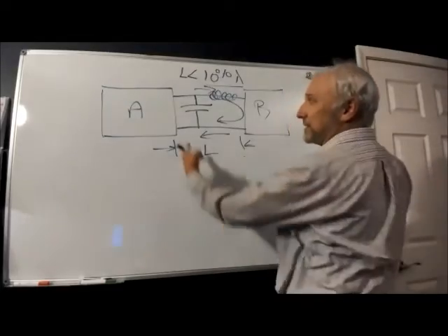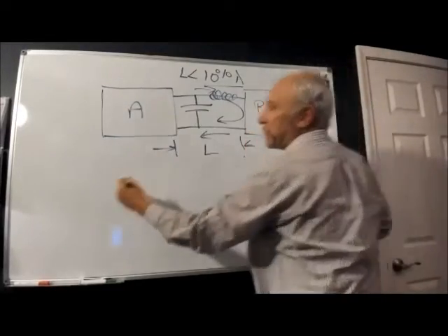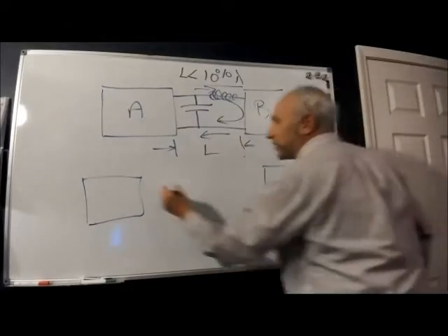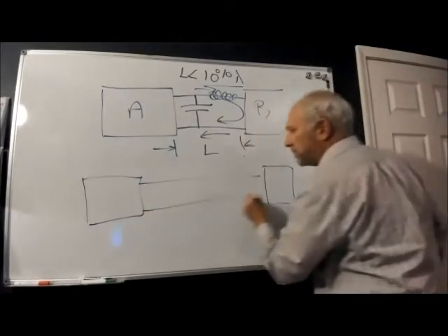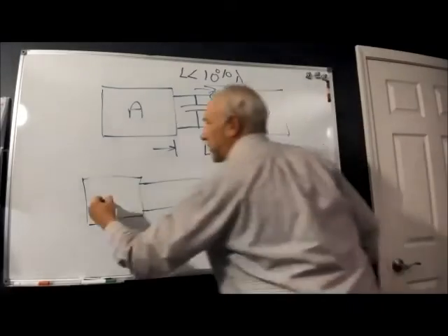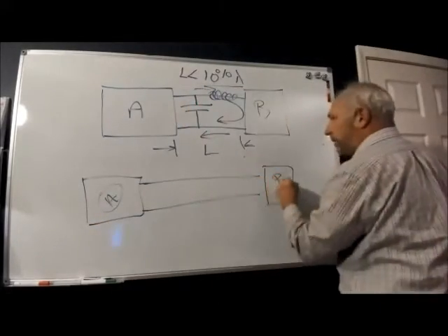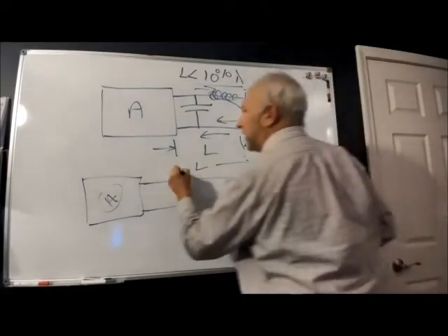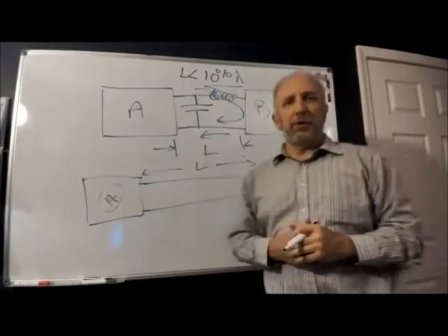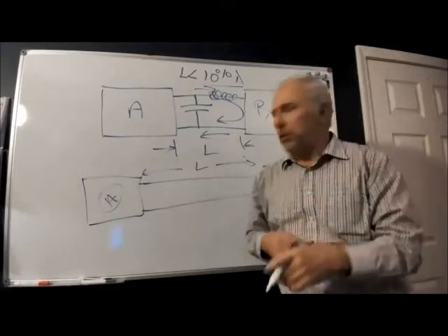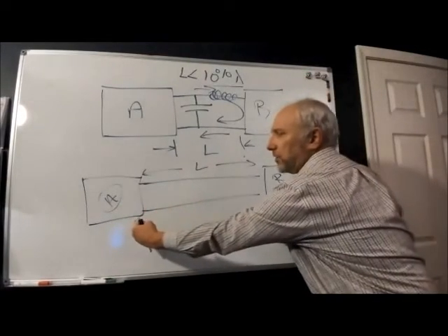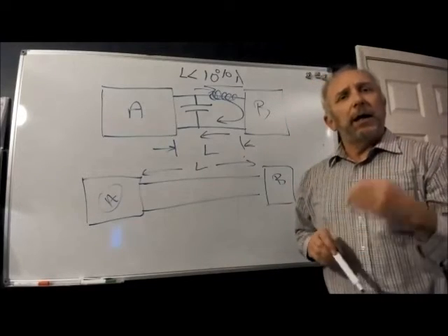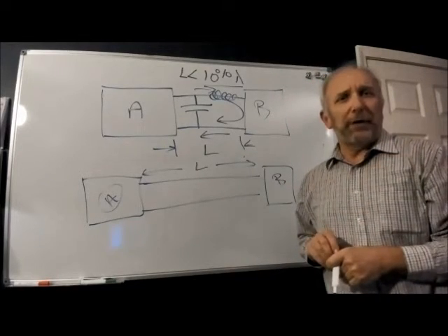So let's spread these apart now. I'm going to take A and B, and on the schematic, these still look the same. But now my physical length L here is greater than 10% of a wavelength. When this is physically greater than 10% of a wavelength, we effectively get current and voltages that are out of phase.